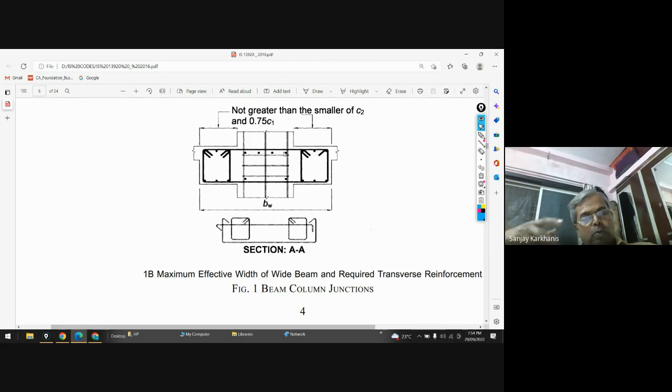Most of the time you will see that near the support you have hogging bending moment, so the curvature is in a hogging sense. That means you need reinforcement applied at the top, and detailing will be such that you can provide it.